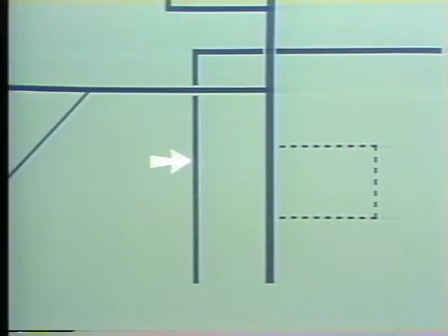These are 3-inch pipes. 1-inch pipes, a pipe that does not join the system, and instrument lines. Knowing that these are instrument lines, you could expect to find some sort of instrument, such as a pressure gauge or temperature indicator at the end of the line. Apart from the size of the pipes and the function of some of the pipes, there's not much more information that can be obtained from this print.